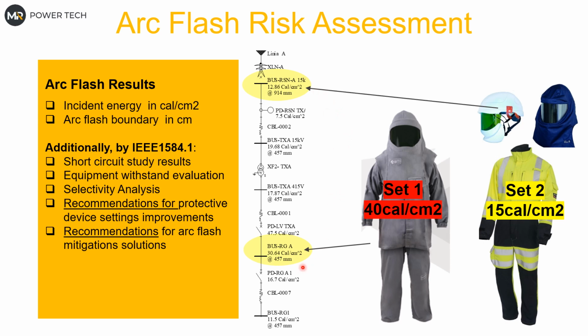It also depends on the situation that arc flash behaves a little bit differently on the low voltage side, or actually it behaves the same. It has almost the same arc voltage drop, which influences the arcing current versus short circuit current.